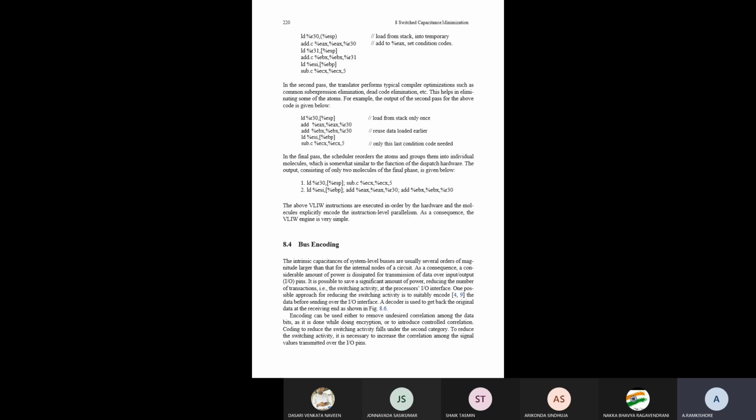That means 2 power n different n-bit words are mapped to a larger set of 2 power m data words of m bits. To perform these operations, we have two alternative choices. One is that the encoder and decoder may be memoryless or may use memory elements for encoding and decoding. If an n-bit word has a unique m-bit code word, then neither encoder nor decoder requires memory.